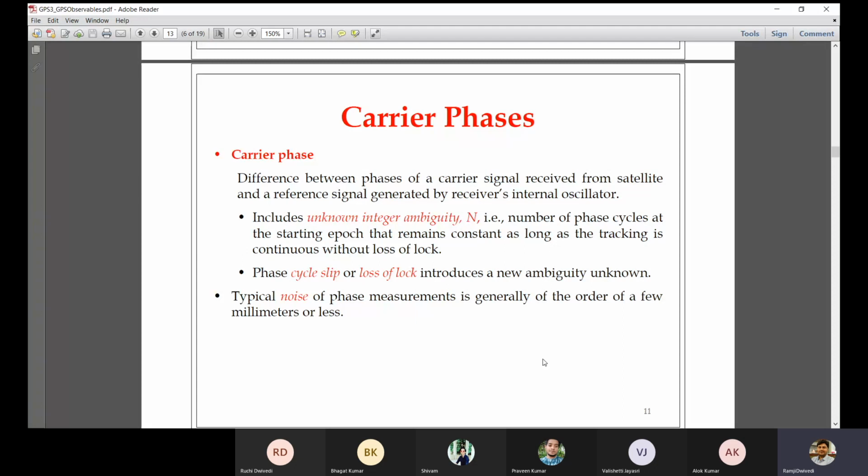travel. At the same time, it also reads the handover word, to know which particular segment of the P code has to be opened. You know that the P code is a week long code. If, let's say, you have switched on the receiver on Wednesday, the Wednesday segment has to be opened for finding another correlation for P code pseudo ranges. But for the time being, forget about the P code, just focus on the CA code only, that has to be correlated for time of travel estimation.